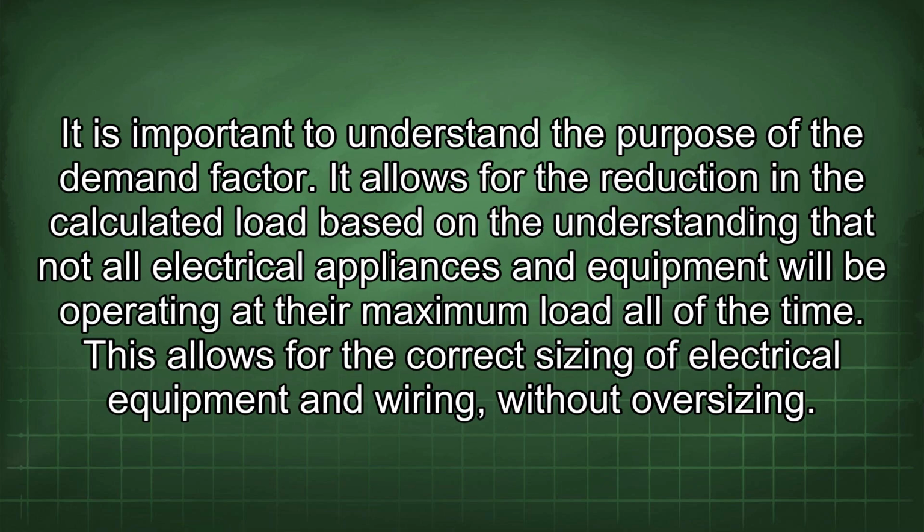It is important to understand the purpose of the demand factor. It allows for the reduction in the calculated load based on the understanding that not all electrical appliances and equipment will be operating at their maximum load all of the time. This allows for the correct sizing of electrical equipment and wiring without oversizing.